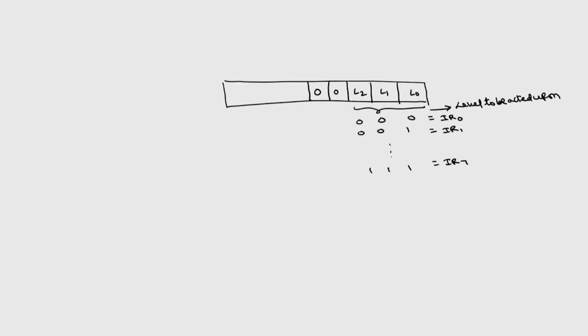The next 3 bits are going to decide the mode. This is called R bit, rotation, it is going to decide the rotation, then SL bit, EOI bit, and this is of course A0 bit which is 1, so these are D0 to D7.